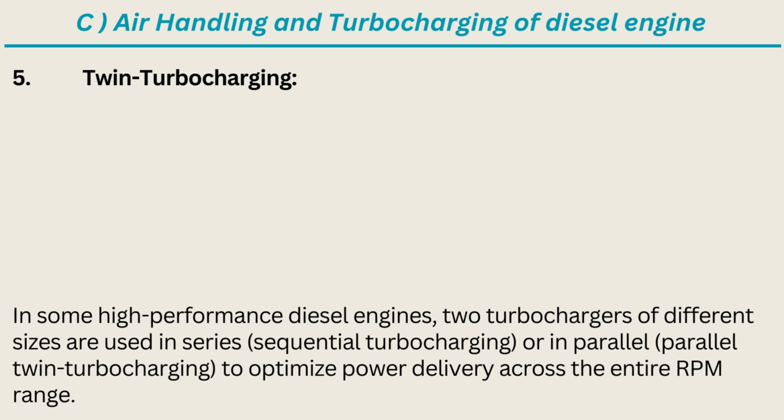5. Twin turbocharging. In some high-performance diesel engines, two turbochargers of different sizes are used in series, sequential turbocharging, or in parallel, twin turbocharging, to optimize power delivery across the entire RPM range.